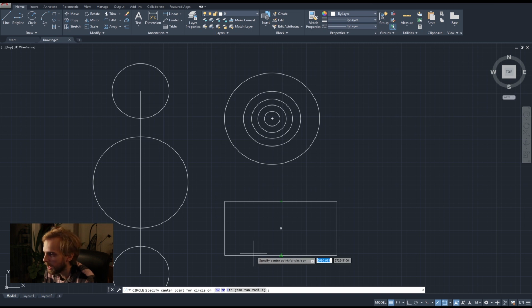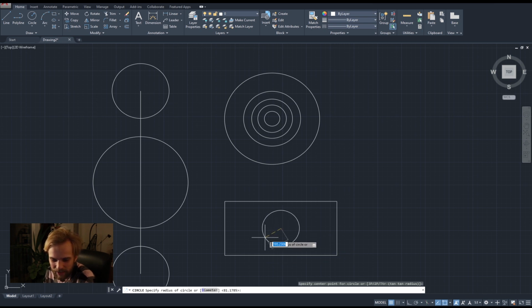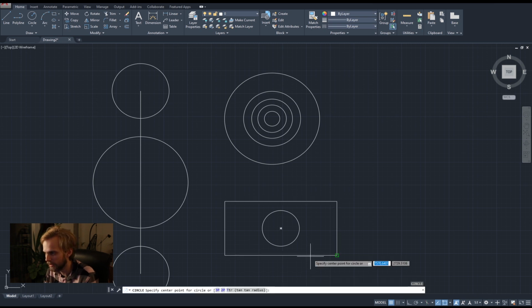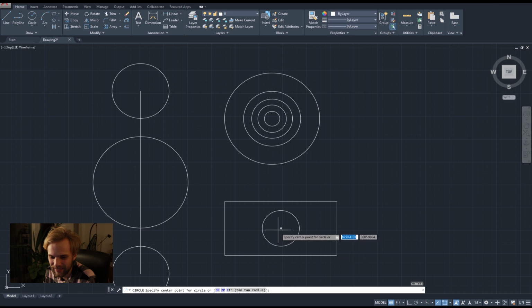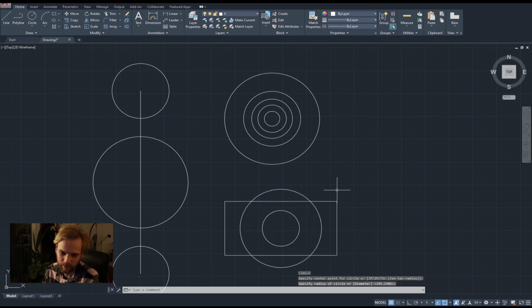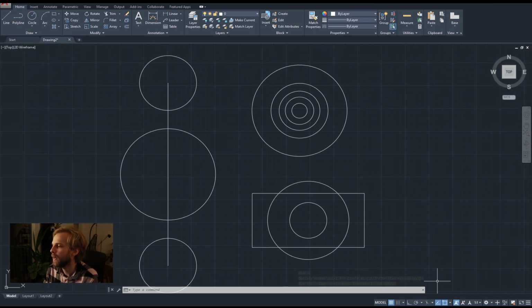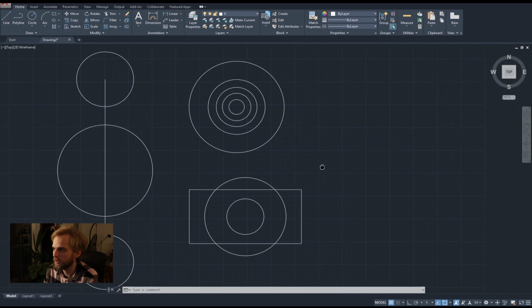But if now I hover my mouse close to that snowflake, now I'm able to snap, right? I'll repeat it again, hovering my mouse, finding that until I see that snowflake appear, clicking on it and dragging out like that. Okay, so that's geometric center.